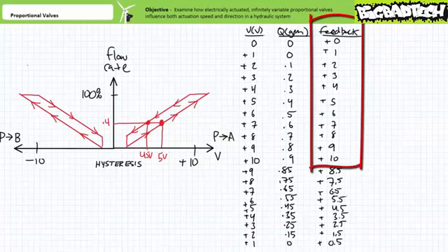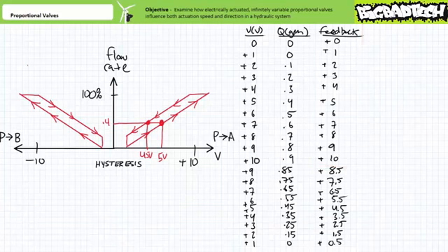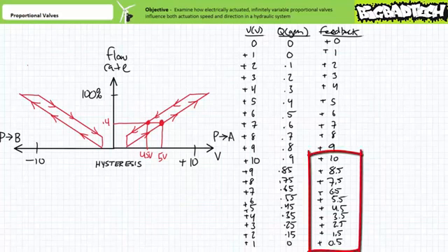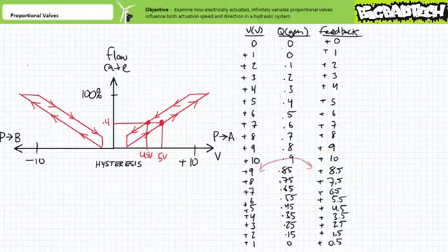On the way from 0 up to positive 10 volts, it would produce the following outputs. Fully open at positive 10 volts and allowing 0.9 gallons per minute through the valve, the spool is fully open and the LVDT produces a positive 10 volt output. On the way down, however, the spool position kind of lags behind the dropping applied voltage. A simple way of internally compensating for this hysteresis lag is to simply compare the externally applied voltage with the internally generated spool position feedback.